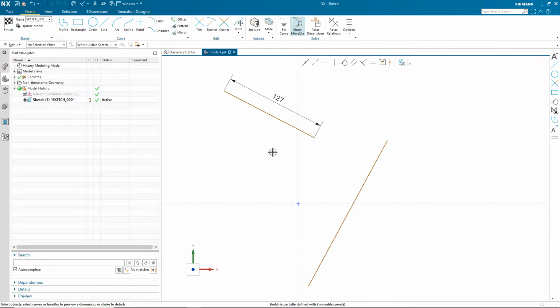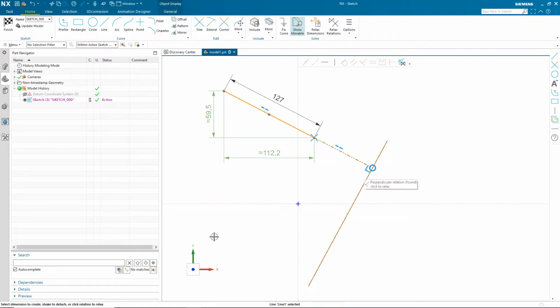There are certain relations that today need to be connected. It's easy to just put the remoteness on it by doing what I like to call creating reference curves, which is something I didn't do a lot of with the legacy sketcher that I do now. So if I click it onto that line, and I pick this line and say make it reference, now if I pick that, you'll see it honors that perpendicular.